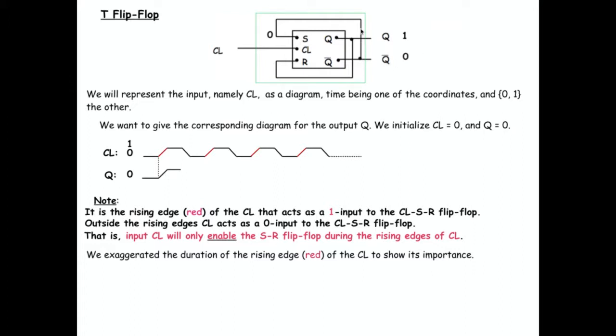And you say, oh, but now Q prime will go into set, but it won't. It will not go until the next, until clock hits 1 again, right? So for now, Q is going to stay as 1 at least until the next clock cycle starts.